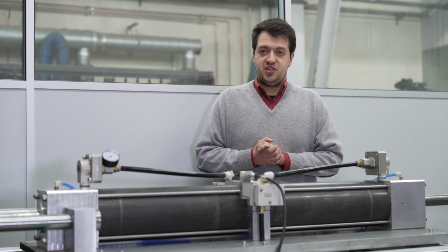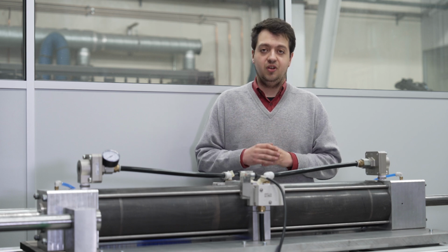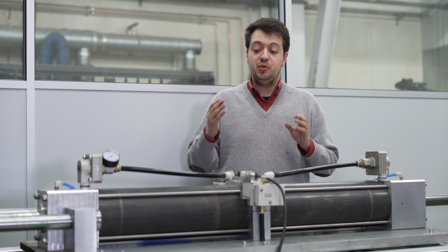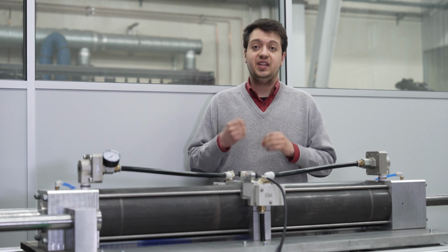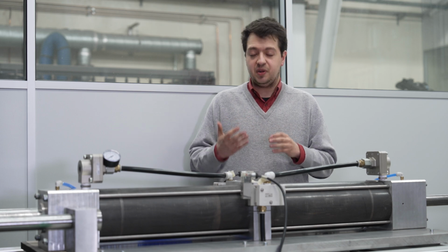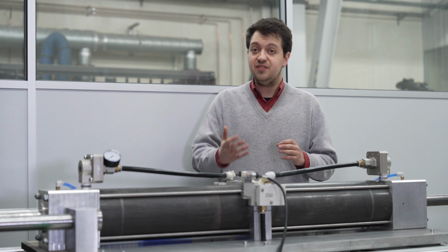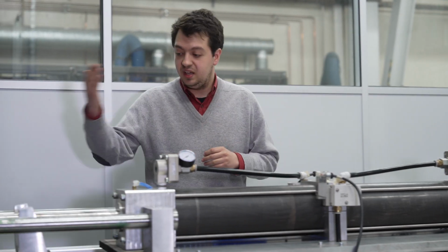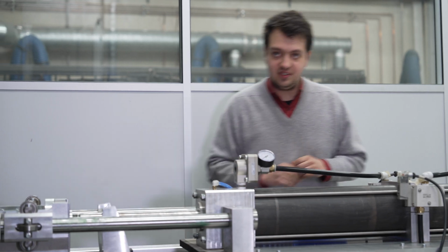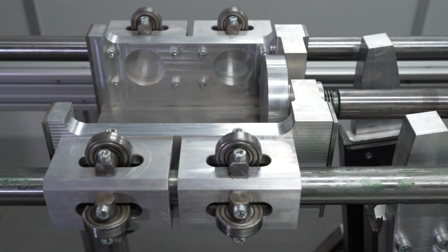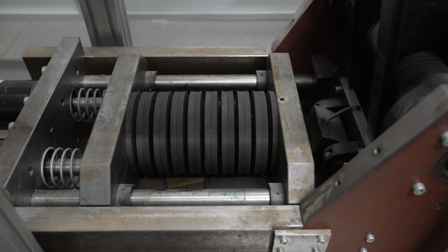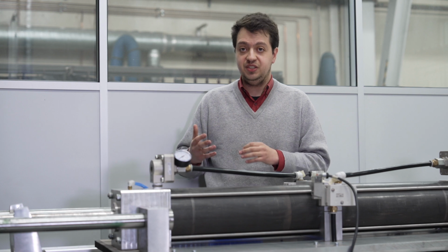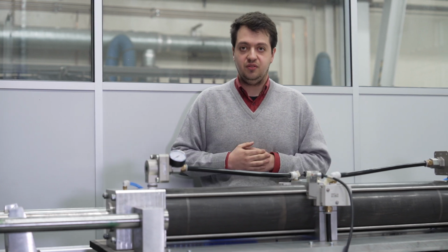This split Hopkinson pressure bar was specially designed to perform tensile and compressive tests. To achieve this, we've developed a pneumatic actuator that can move in both directions and can attain a velocity of 90 km per hour in a fraction of a second. Given that this requires a high amount of energy, we've developed a special braking system where a lever converts the velocity into force, and a spring set up with shock absorbers will absorb the remaining energy until reaching a full stop.